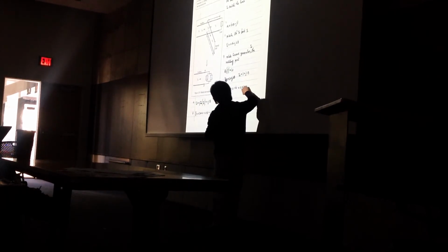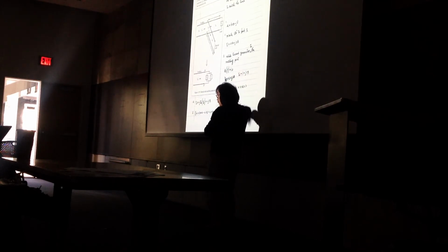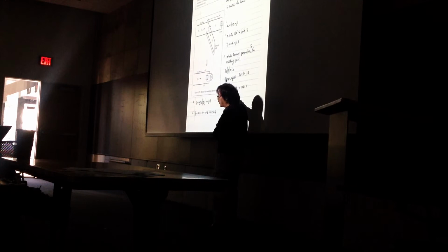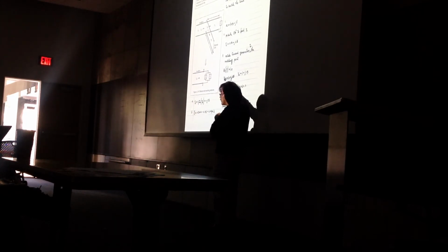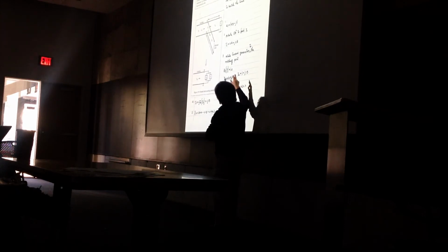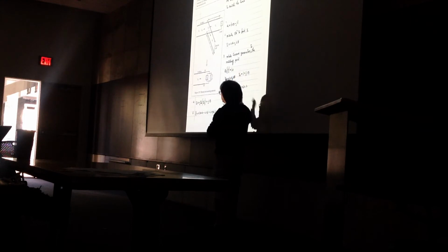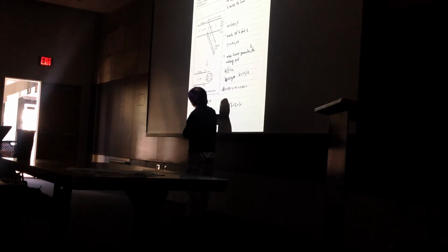Okay? So you need to provide, but here is the distance, answer your question of how far you can travel. You read from your Smith chart the radial line, and that's 0.178 lambda, minus the original one, 0.116 lambda, which tells you that you need to move toward the generator by 0.062 lambda. Okay? Now, this is your matching.